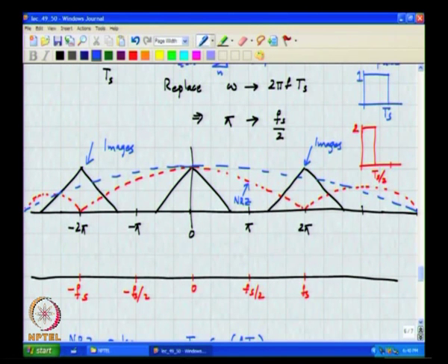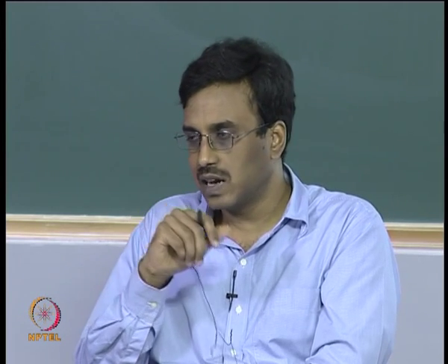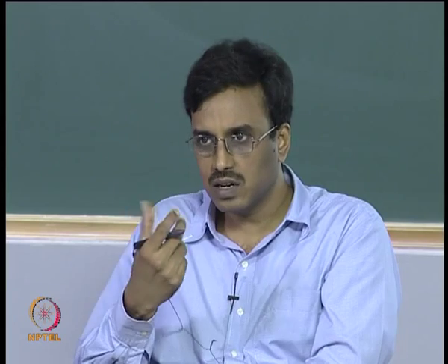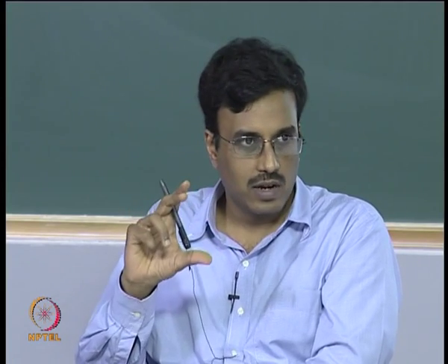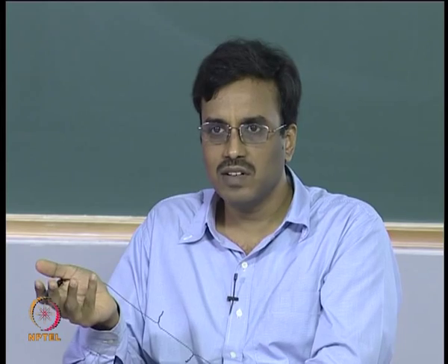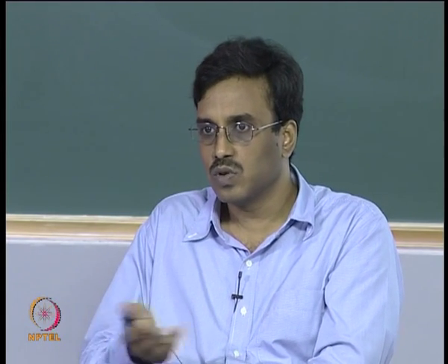All right. And that makes sense, because a return to 0 pulse shape has much larger transitions, and these transitions occur twice every period. You understand? That means that the jumps going up and down are much larger in the return to 0 case, which also means that it must have much higher strengths of high frequency components. So, the spectrum actually makes sense.